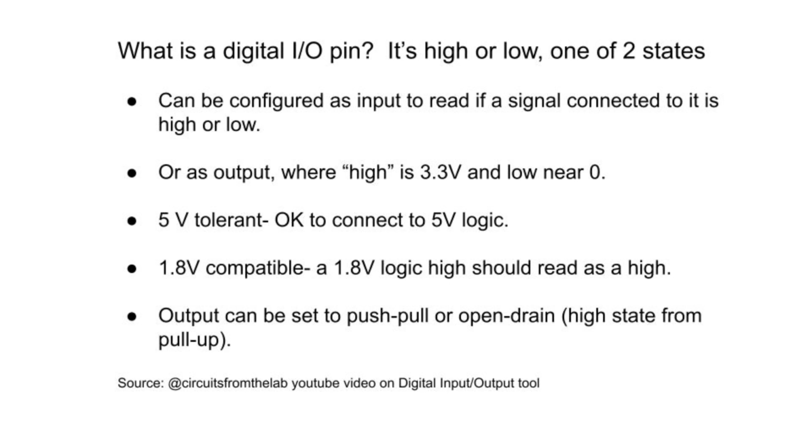And finally, the output can be set to either push-pull or open drain. The latter is an advanced topic that I won't go into in any detail, but it basically means that the high state comes from a pull-up, and multiple sources could pull the signal to be low. For example, I2C might use that.